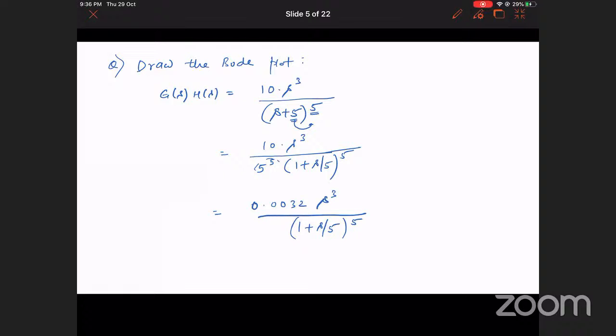The next step, guys, you arrange them in the ascending sequence. If you remember the sequence that I have made you understand, first of all you have to identify poles at origin or zeros at origin. In this case, there are zeros at origin, as you can see, s cube.